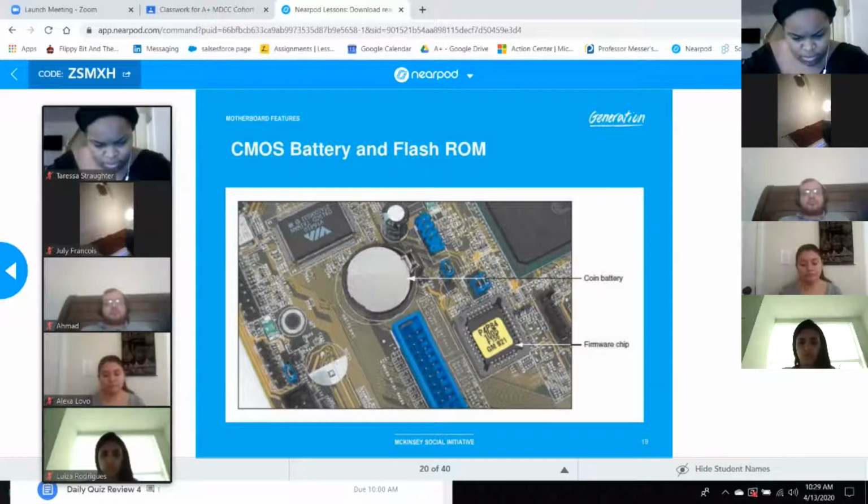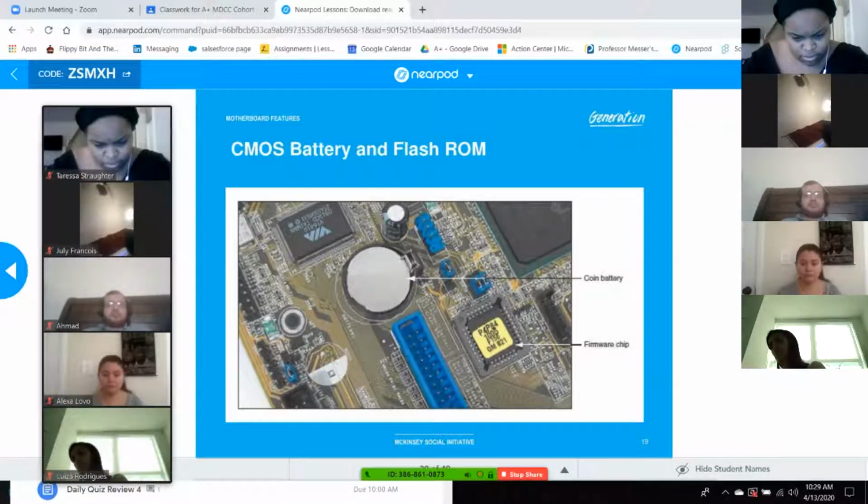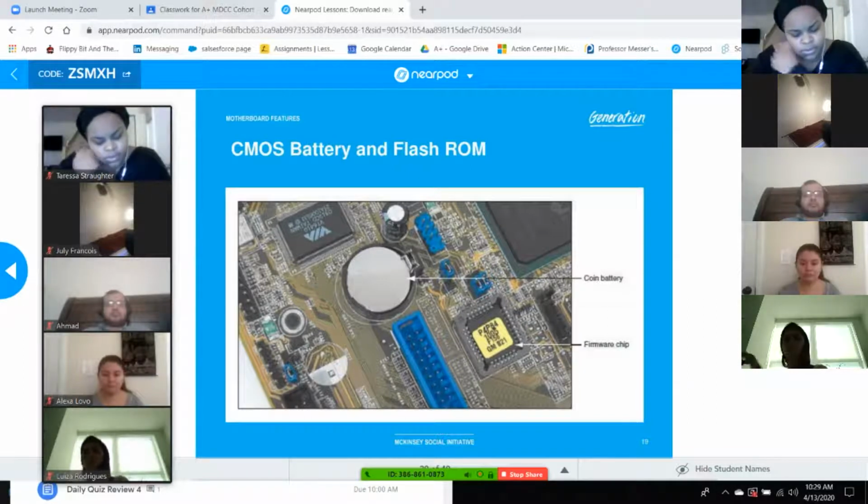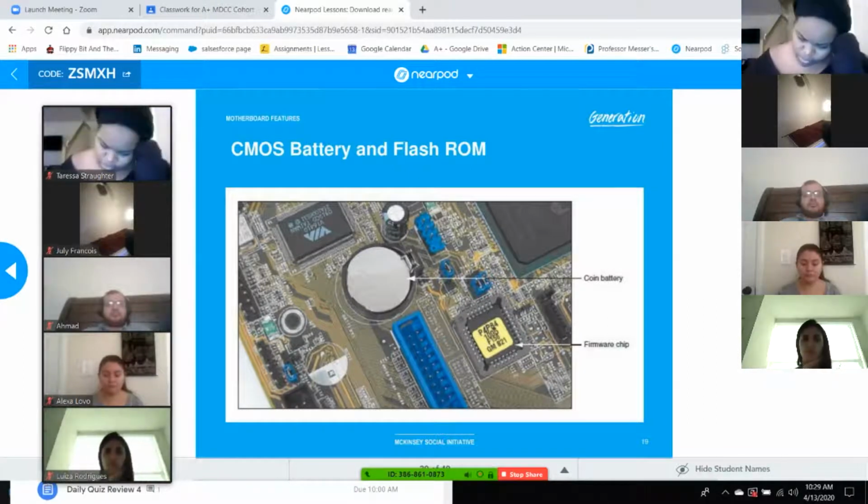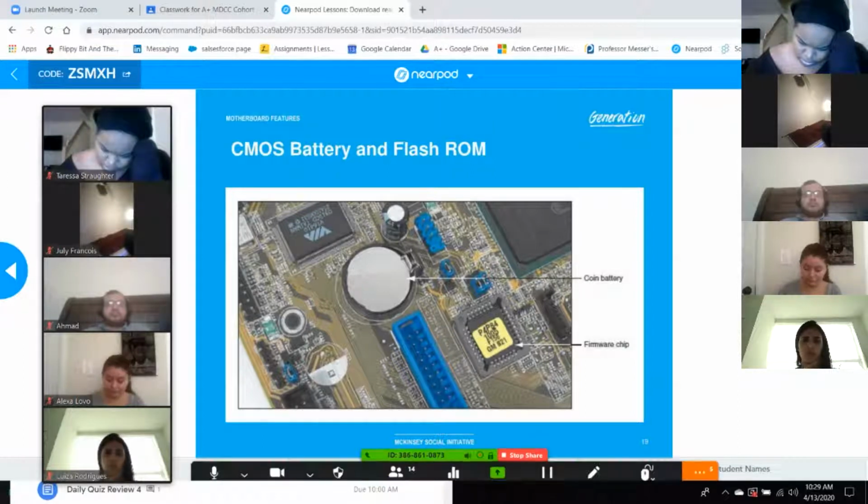The moment you start losing your time or configuration every time you turn your computer off and on, you can bet you've just got to go and buy this little thing. Like I said, you can buy it pretty much anywhere. You'll see these little circle batteries everywhere. You push back on this little device here with a small screwdriver, and with ease, you should be able to pop it out. Then the same thing, you push it in and it locks into place by itself. It has a spring load there.